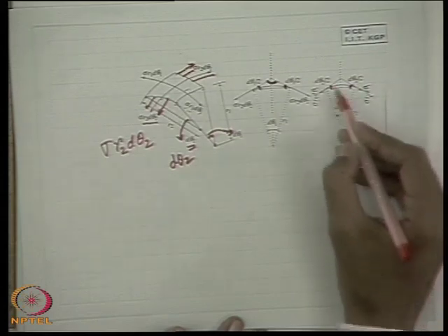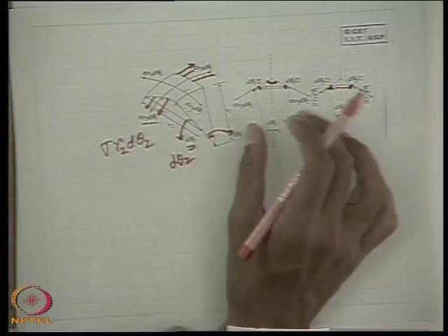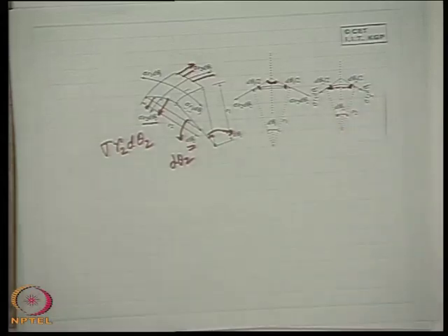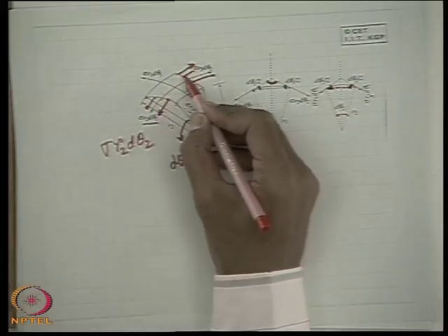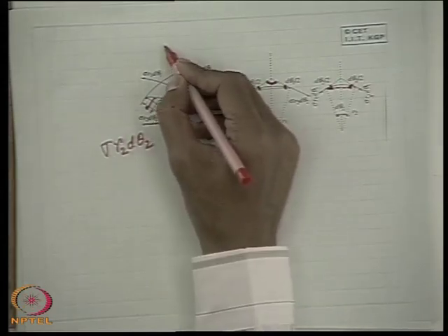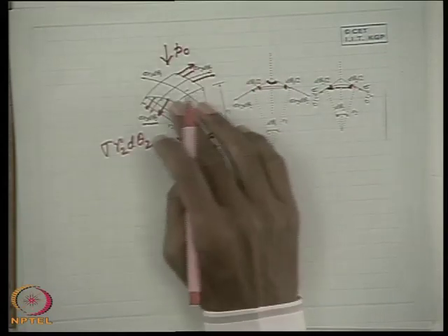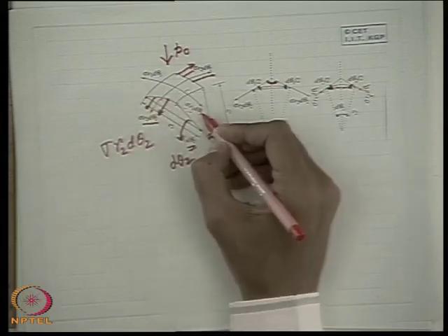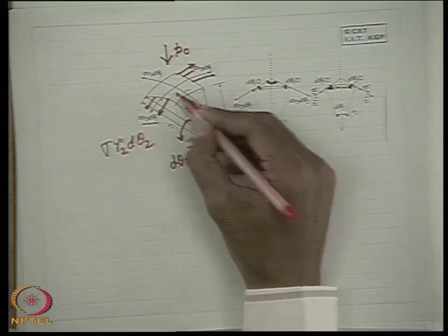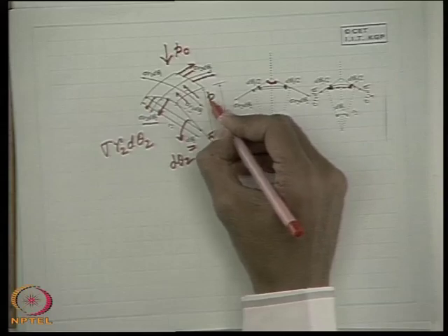Now let us write the force balance, assuming that the convex side of the liquid surface is acted on by a uniform pressure P0, the pressure of the gas, and in the interior of the liquid the pressure is Pi, acting perpendicular to these surfaces on the concave side.